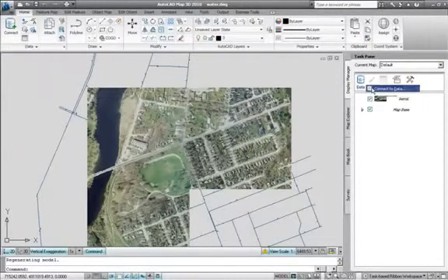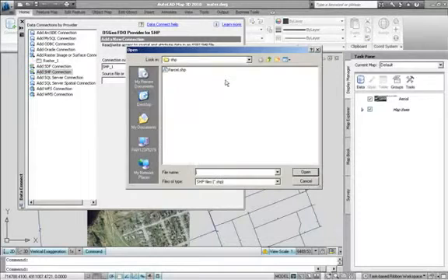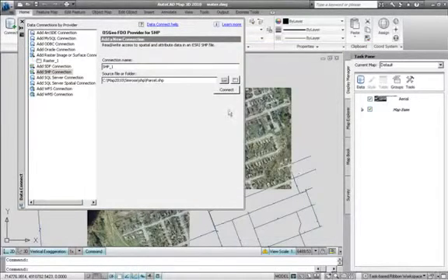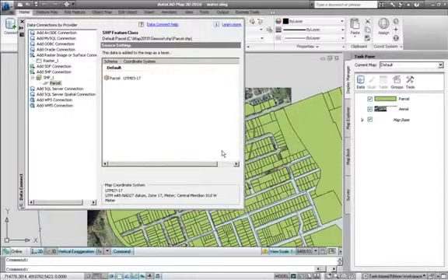You may have land parcel data held in Esri shapefile format. Instead of getting the GIS department to spend time translating a section of the data for you, simply use open source FDO to connect directly to the same file used by the GIS department. AutoCAD Map3D also understands over 3,000 spatial reference systems, so even though the parcel data is held in a different geographic coordinate system to the base map, the data is transformed on the fly to fit it into the correct geographic space.